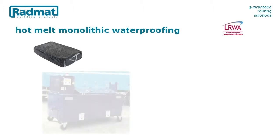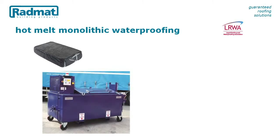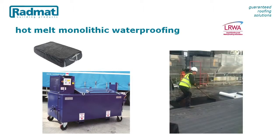The key is to have an agitating melter, as this keeps the component parts of the hot melt mixed together throughout the installation. When installing hot melt, the melters create the main health and safety concerns. They typically use propane gas to heat the air that melts the blocks. It's all self-contained, but requires covering by a suitable method statement.